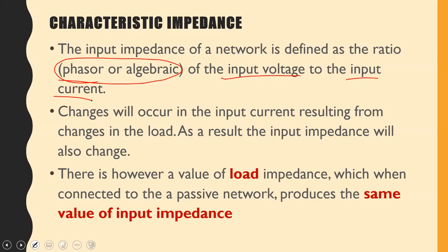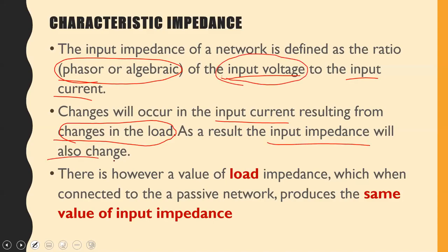So if you change the load, and you're changing that load because the higher volume is requiring more power, in a sense you're really changing the loading. And by changing the loading, the input current is also going to change. So if the input current changes, assuming that the input voltage remains the same, then the input impedance will also change. Everybody agree with that?